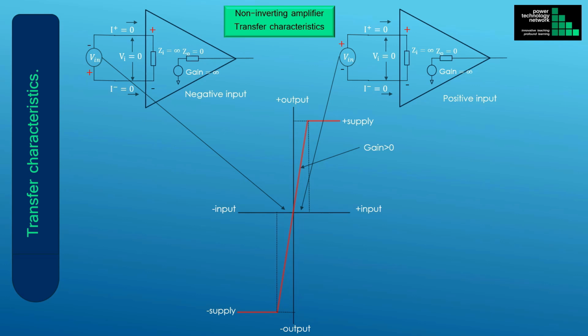When the positive terminal of the input voltage source is connected to the positive terminal of the amplifier input, the gain is positive and the input voltage is positive, making the output voltage positive, as shown in the first quadrant. The operation is in the first quadrant, and the input voltage ranges along the x-axis, as shown, with the output voltage ranging from 0 to the positive supply rail.